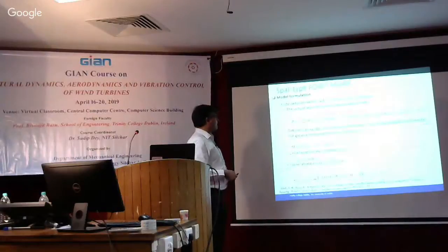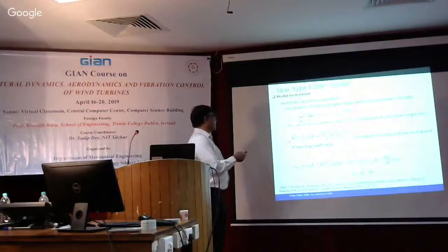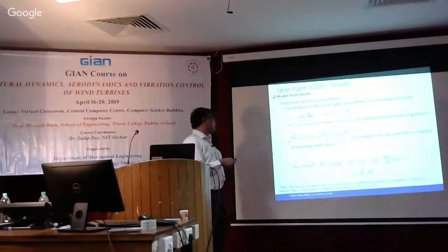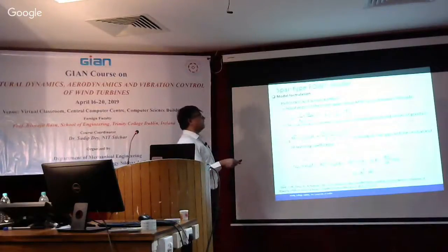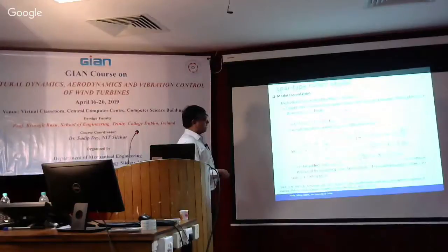So if we do this and calculate all the loads and analyze, first of all, we do the hydrostatic analysis and find the initial depth of the top of the spar below the mean water level. Simple Archimedes principle. Buoyancy, make sure this is stable. This is actually the distance between buoyancy and the center of gravity. And then, obviously, we want to find out the heave and the roll restoring coefficient based on the springs that we have seen. So we do the basic fluid, not even dynamics, actually statics.